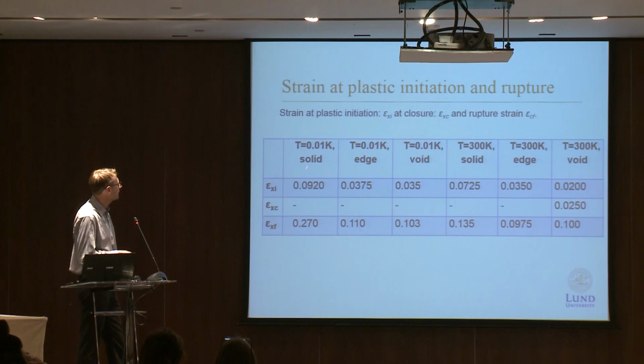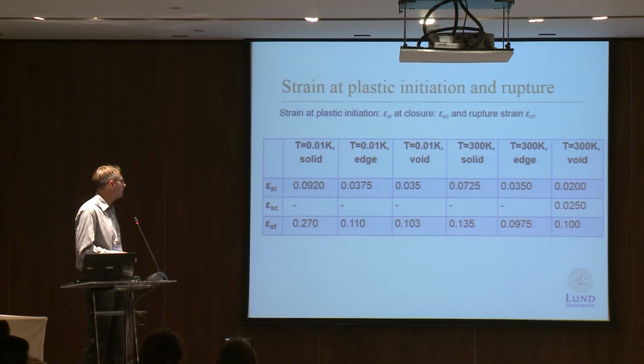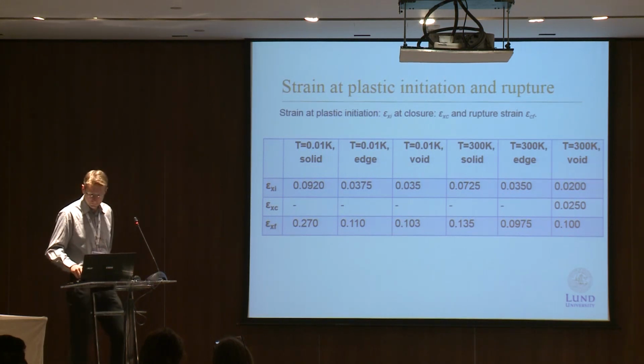If we now compare the lower temperature to the higher temperature, we can see that in all cases the strain gets lower when we increase the temperature. So we can withstand lower strains. And in some cases quite a large difference. For instance, this solid beam, we only have half the strain at failure at the higher temperature.